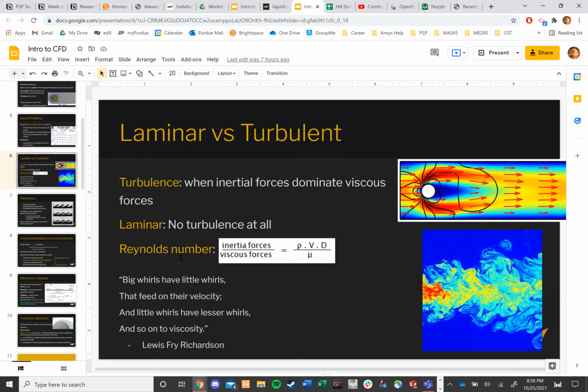And if the Reynolds number is really high, in the thousands, let's say, it'll become turbulent because your ball is basically tearing apart the air. I guess that's maybe not the best way of describing it, but it's a good way of visualizing it. The air is no longer able to really hold itself together with its viscosity, and it just gets thrown around like this.